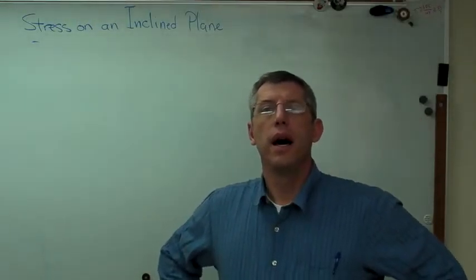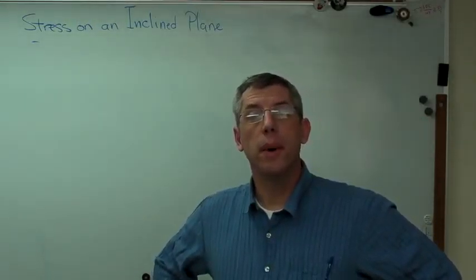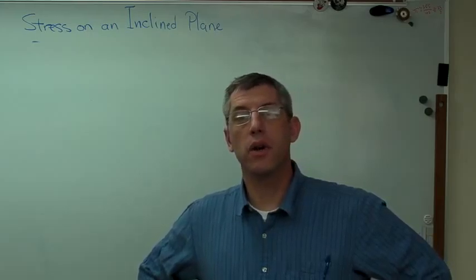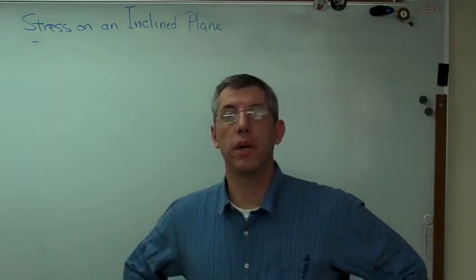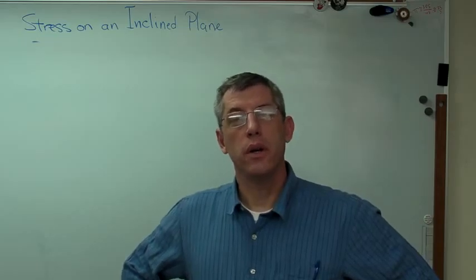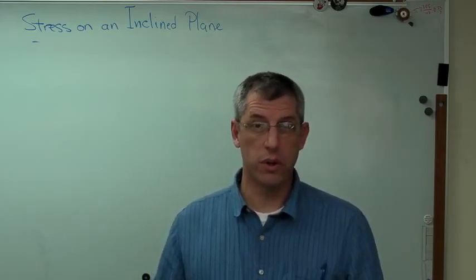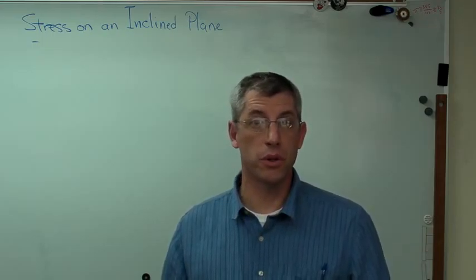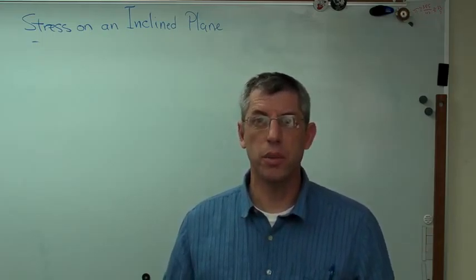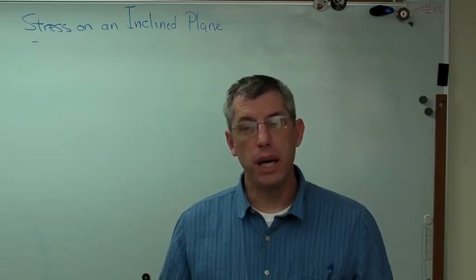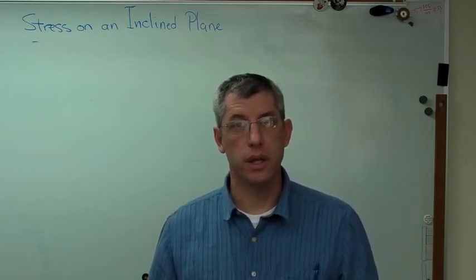Hello again. I've had a request to talk about how to calculate stress on an inclined plane. That sounds like a pretty good idea. So here you go. Stress on an inclined plane, by the way, is the basis of Mohr's circle. So if you want to figure out where Mohr's circle comes from, this is a pretty good place to start. Now, the big idea here is that stress is directional.